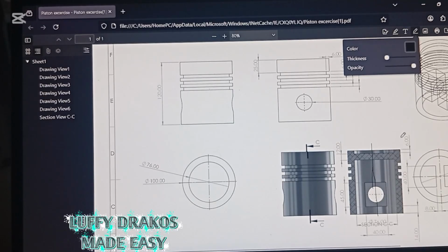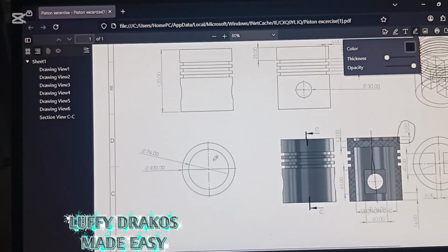Since we're going to be using revolve as the main part of getting this round piston figure, take note of the dimensions. 6 for the distance between the top layer, then the first circle is radius 100 and the second is 76. Since we are using the center line, you divide them by 2, get your answers. Also take note of those in between drills that are separated by 6 millimeter.